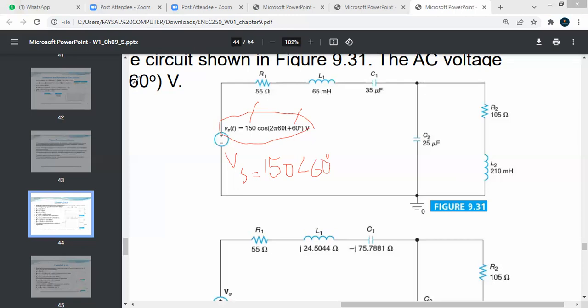Okay, so this is the first part, that I have to convert my first value, that is my Vs instantaneous value, into a capital Vs, which is my voltage value of my source. For a source there are two things: first is my amplitude value, and second is my phase value. This is for the voltage source.